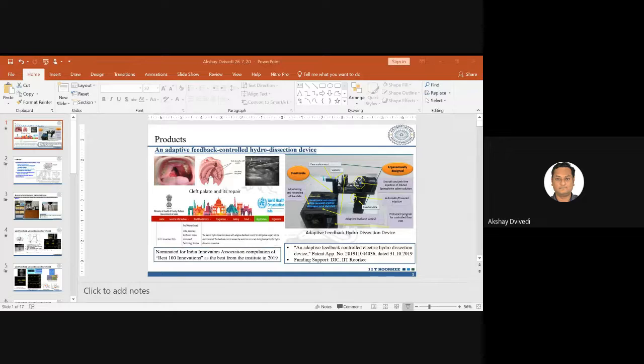As we work with conventional electrochemical discharge machining, that same procedure comes here. The only thing is, a manipulator is moving this work so that it is being fed into the tool. And while that is happening, it is creating a sort of slit in the work material.